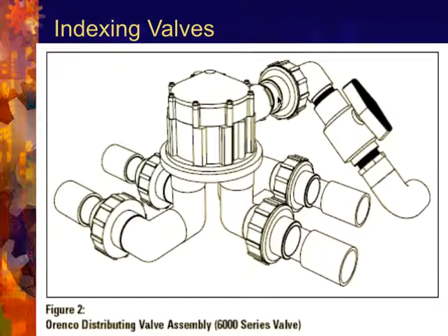So what will happen each time this pump comes on, there's a cam inside that's pushed down. It's spring loaded and it's pushed down where it only has one opening or a slot that allows water to go out only one of these openings. When the dose is over with, the spring then pushes that cam up and it rotates the next position so that when the pump comes on again, the cam drops again, but it will have rotated, say, from this position to that position, and it'll just continue to do that same sequencing and rotate all the way around.